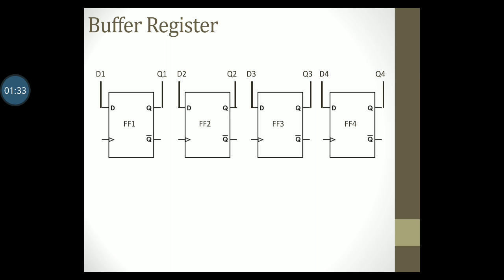What is important to draw now is the clock signal. I have used positive edge triggered flip-flops here, which can be seen from the arrow symbol on the flip-flop diagram. What makes these individual flip-flops capable of storing data at the same time is that all the 4 flip-flops will be connected to the same clock pulse.